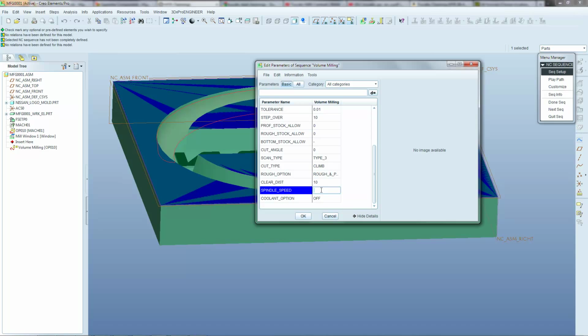And the last one is spindle speed, and it seems we've set the machine with a maximum possible speed of 10,000. Let's just use the 10,000 for this example. Again, you're going to have to justify all these figures by doing a little bit of research and a little bit of reading, and by matching them to the mold material that you've chosen and making sure that's appropriate for the injection molding situation that you've been asked to simulate.